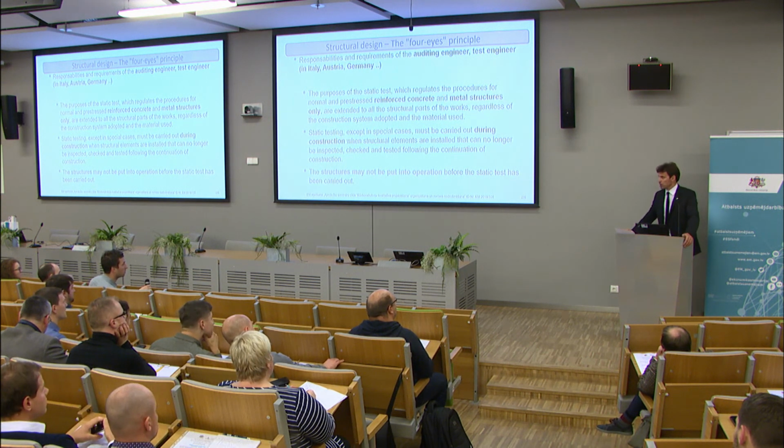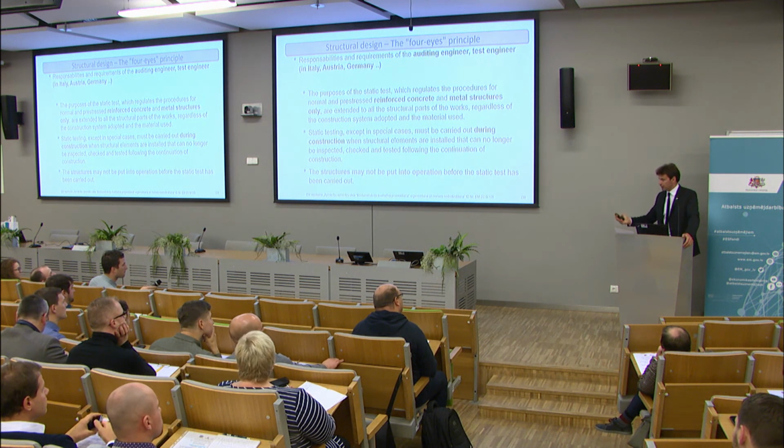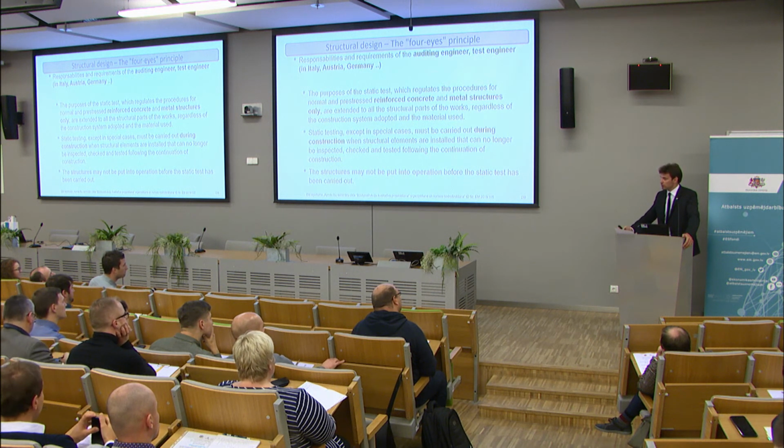No. This is actually something that the reviewer can decide. But in some cases, for bridges, yes, it's done. Usually you load a very heavy truck and you pass over the bridge, you measure the deflection, and you check that it is consistent with the calculations.